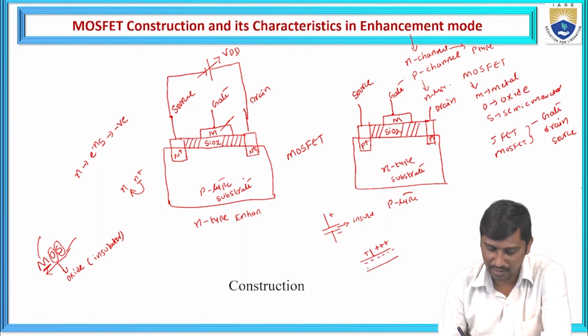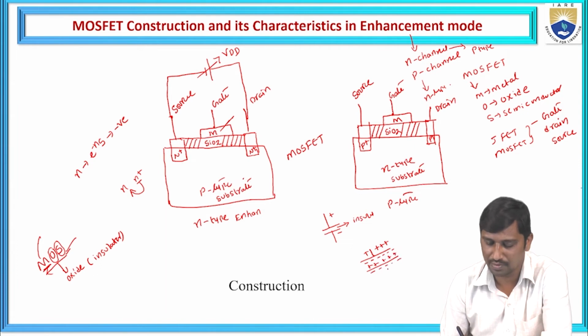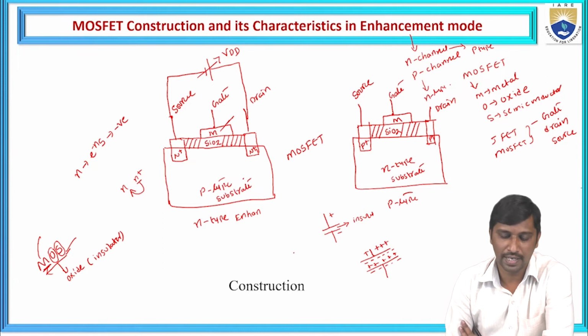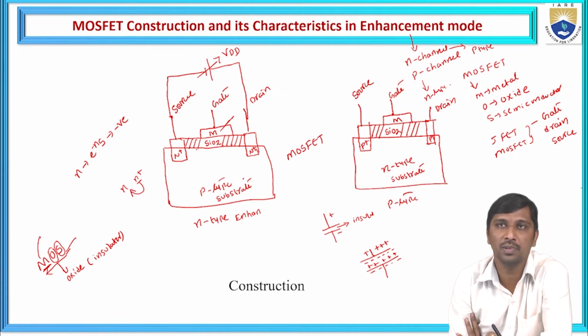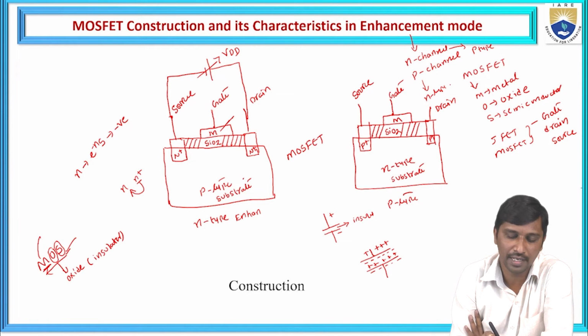Then on the other plate, the polarity becomes positive, and again at the end of this pole it becomes negative. So to establish the negative energy to repel the charge carriers, the electrons, the majority charge carriers of the source, from the source to the drain, we need to establish a negative potential energy. To establish it, the gate should be biased positive with respect to the source.